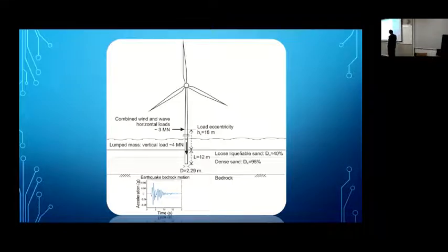And just to give you an example, this is a problem we're going to look at. So we try to drive them into the subsea. The water level is there, and we're considering, say, something like 10, 15 meters of water there. And you got some loose soil on the top, and you try to drive them into dense sand, obviously, because you have to carry the load.